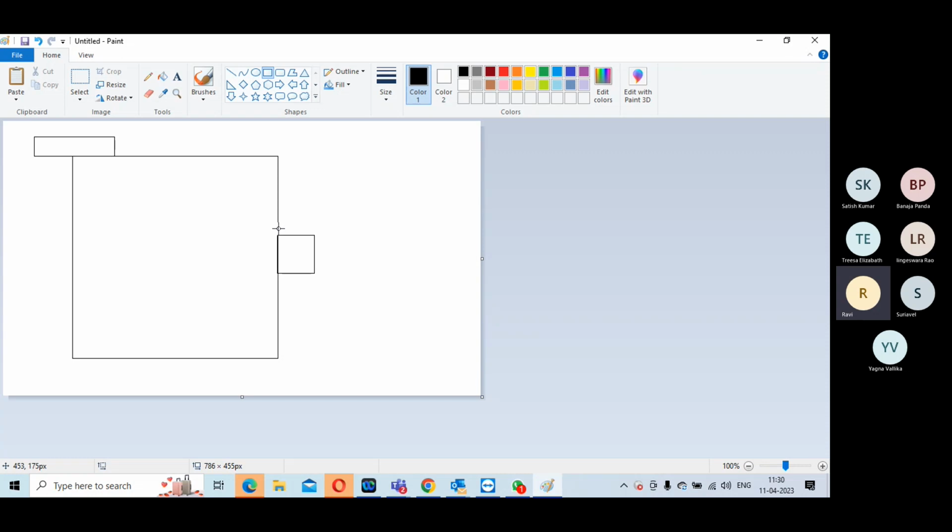So try and place the macro into this, only allowing the pins to have the access, because this is the dummy area given. So you try to utilize these particular notches with macro pins. Better to avoid standard cells.